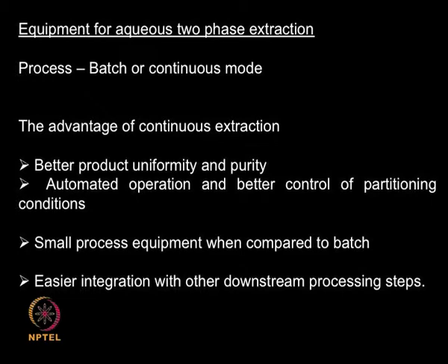So I may have a continuous liquid-liquid extraction, then I may take it to a chromatography which may be operating continuously, I may go to a filter which may be operating continuously and so on. So we can nicely integrate continuous operation, whereas in batch operation you are going to have a product and for some time there will not be any product coming out, and then again there will be a product and so on. So it is going to be start stop, start stop. That will be the main difference between a batch and a continuous operation.